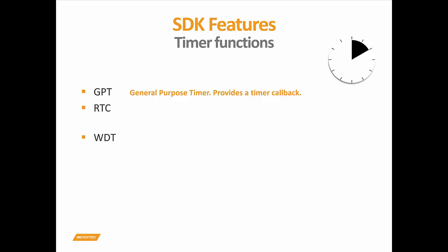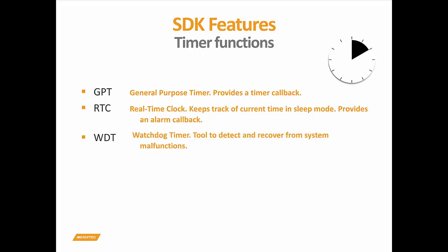We have the real-time clock, which keeps track of the current time in sleep mode and provides an alarm callback as well. And then we have the watchdog timers, which are a very useful tool to detect and recover from system malfunction. If anything goes wrong, they can check if everything's all right and take the necessary steps to get the system back up and running.